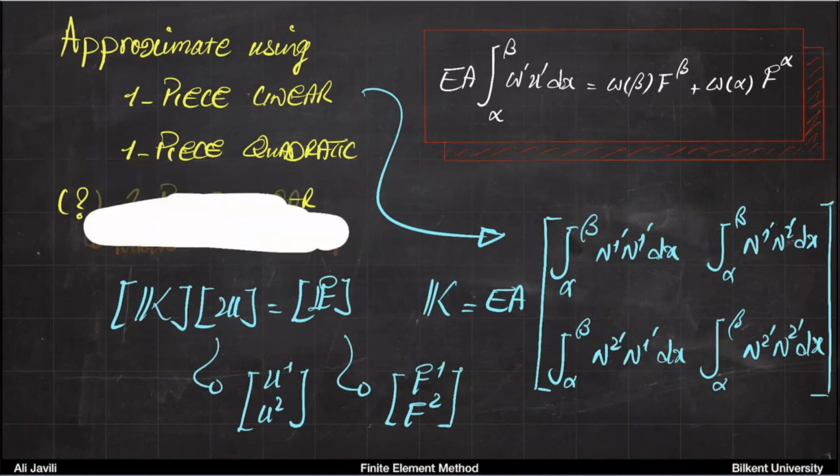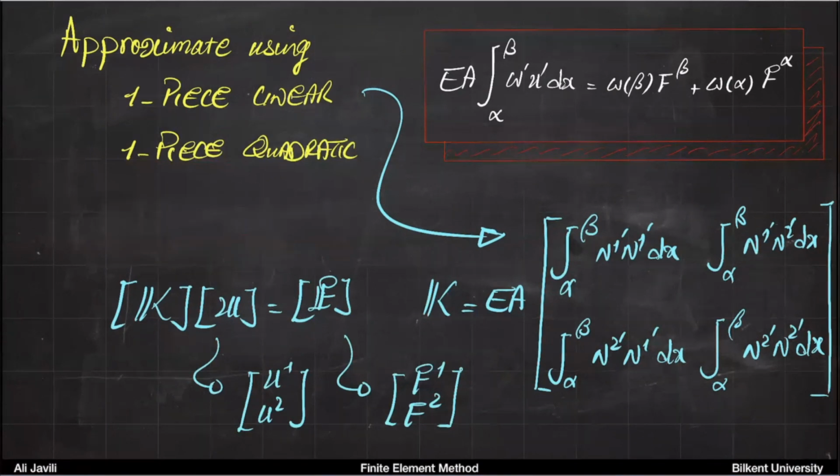Okay, so if you remove that thing, and also remember this stiffness that I wrote here, maybe I can just write it in our form. It's basically K equals EA over L, times the matrix 1, minus 1, minus 1, 1. All right, so you have that.